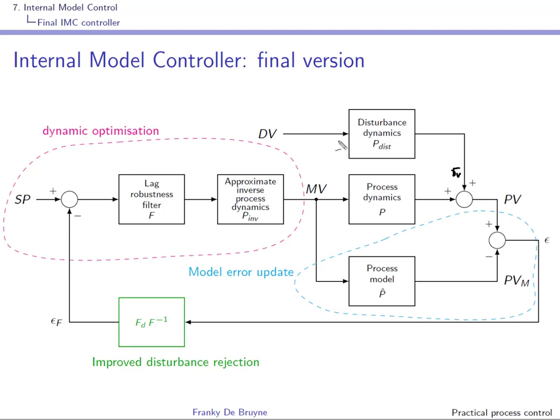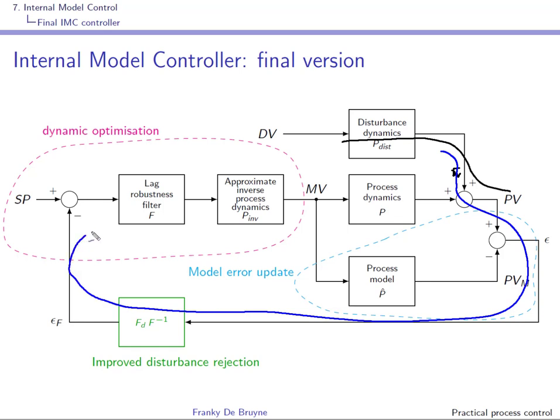So you have one path of influence on PV, but here this PV, right, is also going to influence epsilon, and you have created, using this feedback, a second path of influence, that is this one over here, right? And what you would like to do is to make sure that this second path of influence compensates the other, right? So here we have plus, minus.